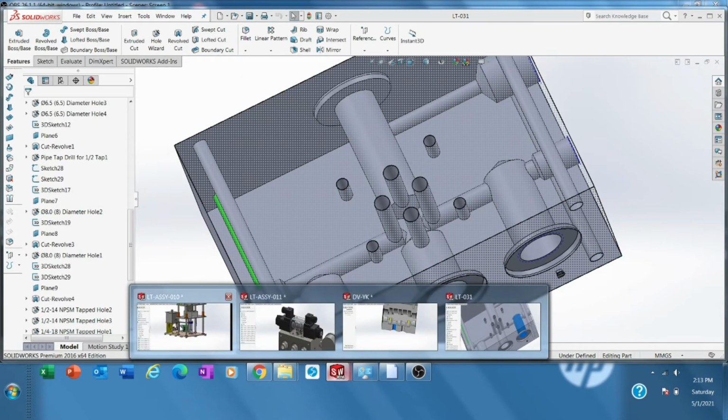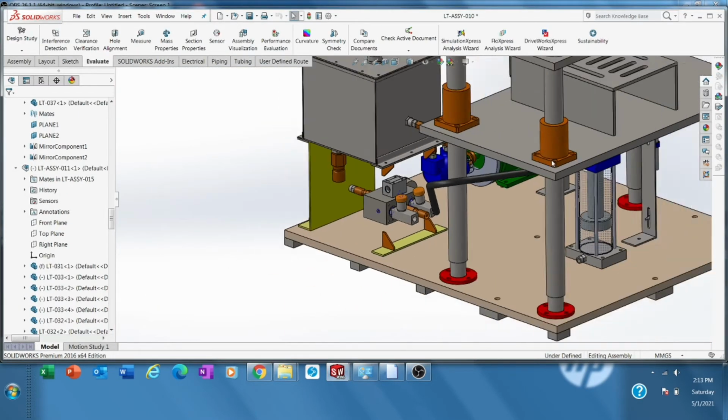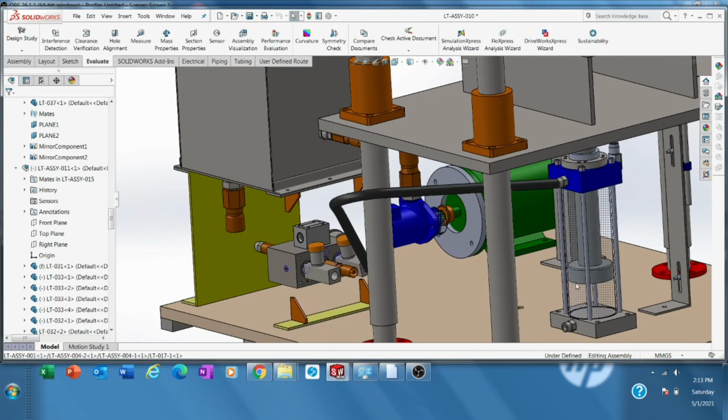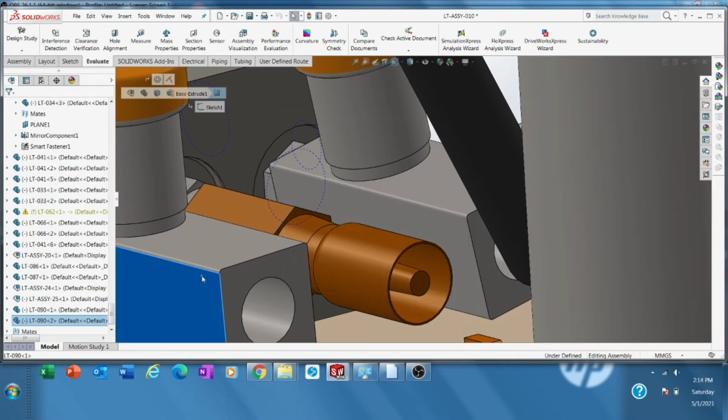And if you check on the main assembly, out here, and then the lifting table will move down. And this is what we call the needle flow valve. So if you want the moving down to be a bit slower, you just choke it. If you want to make it faster, just open it a bit.